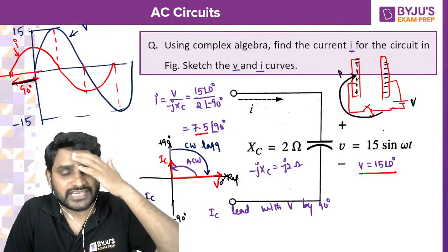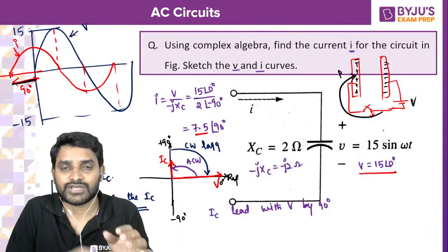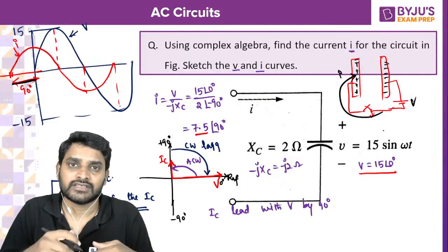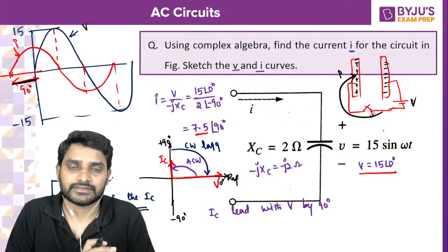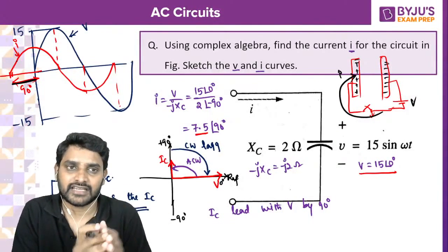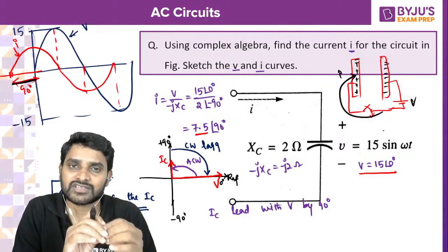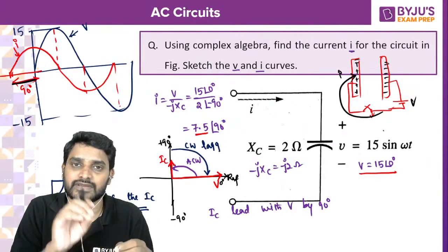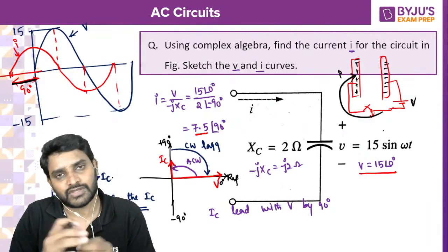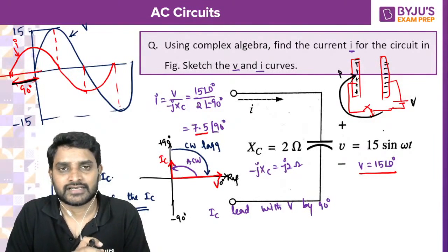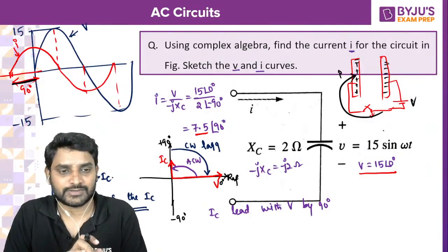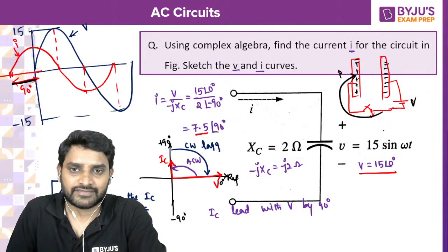Yeah, Ananya, you can say like that. Active power is going to be 0. So the inductor does not consume or dissipate power. What it actually means is P is equal to 0: a pure inductor is not going to dissipate the power. According to the formula also, cos 90 is 0, so active power is 0. Is it clear for everyone?